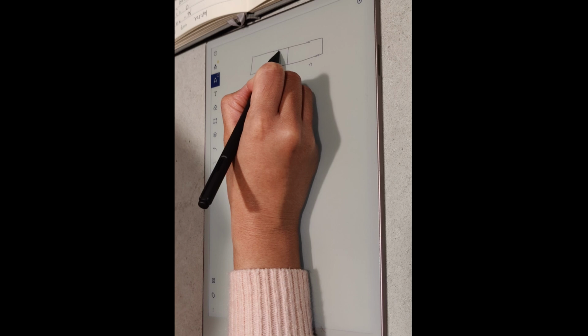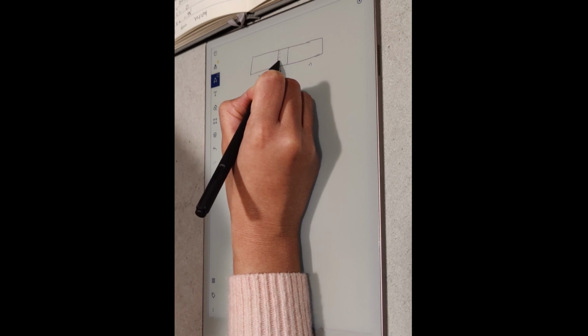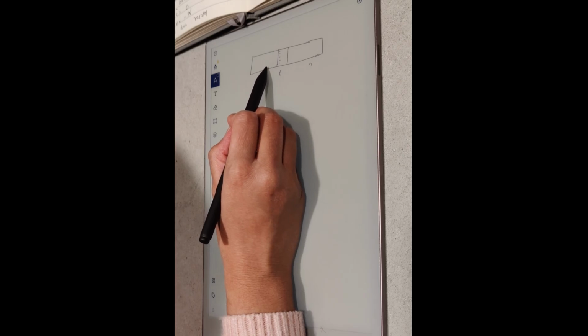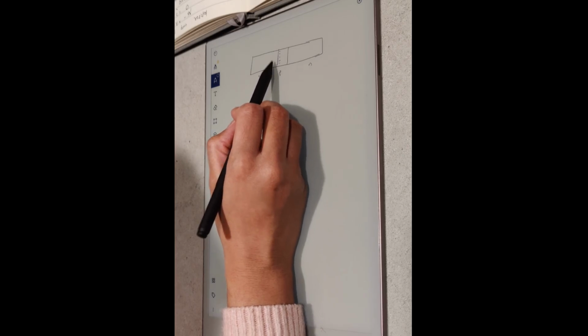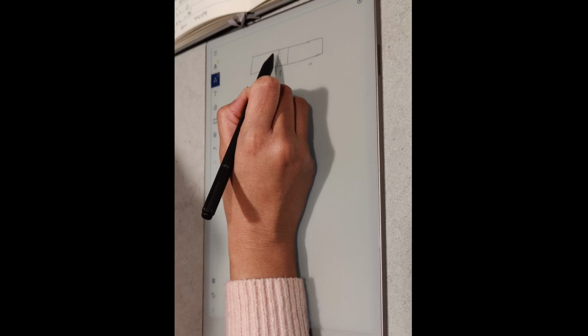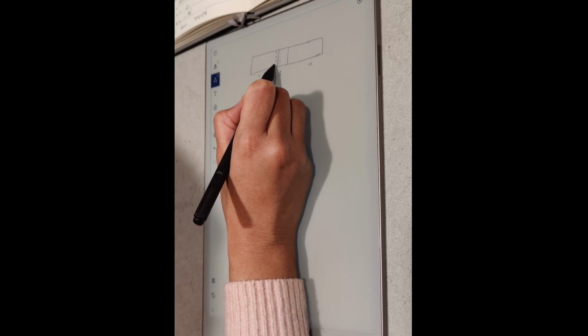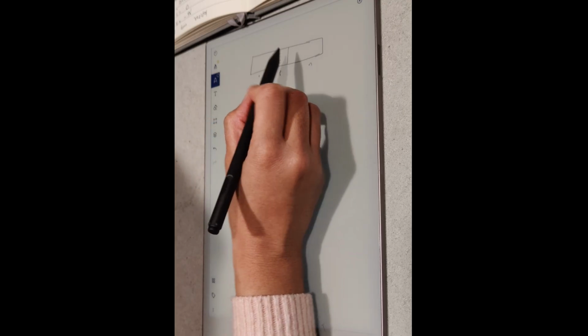Therefore, this P side is going to have a negative charge. Now since electrons have gone from here to here, it created holes. In other words, the holes have moved to the N side, so this is going to create a positive charge here. Same thing on this junction.